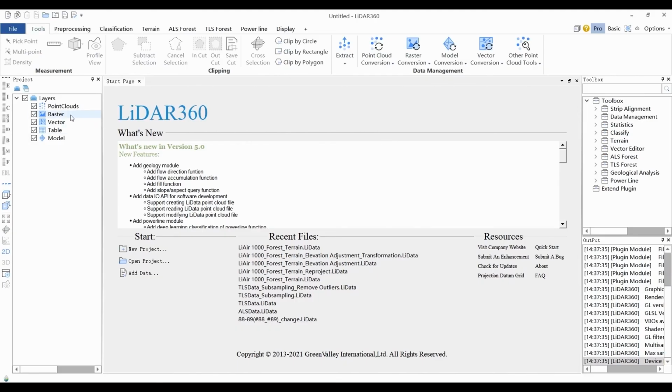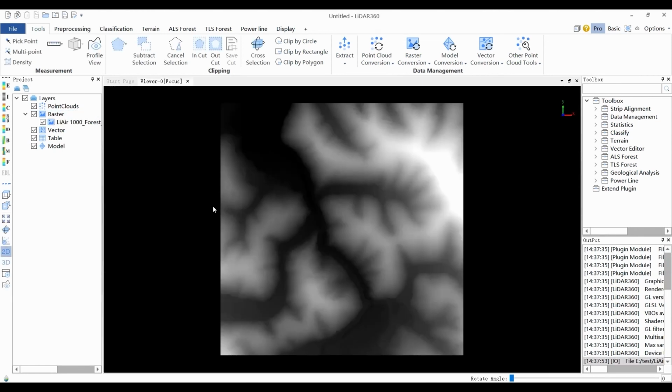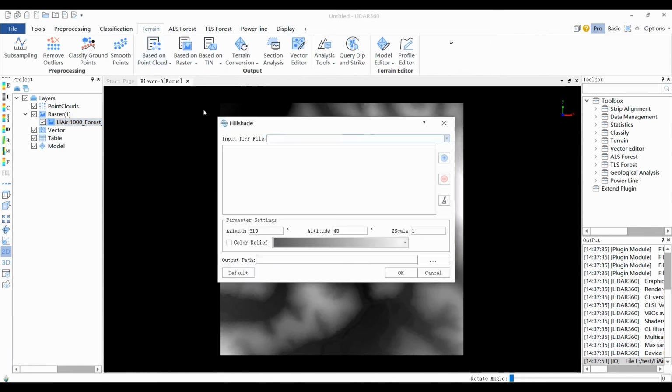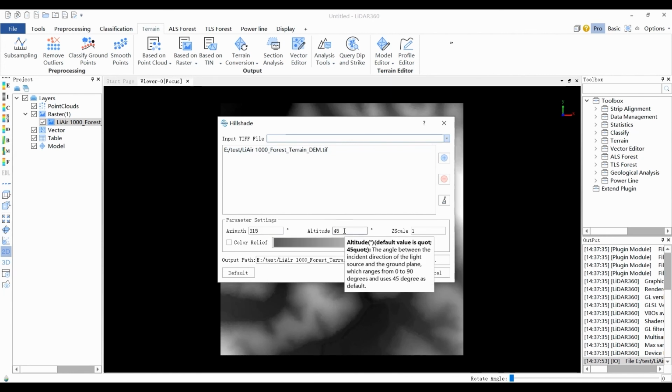The Hillshade tool obtains the assumed illumination of the surface by determining the illumination for each image element in the grid. The assumed illumination can be attained by setting the position of the light source and calculating the illumination value of each image element related to the adjacent pixels in the analysis or graphic display. The Hillshade tool can greatly enhance the surface visualization, especially when using transparency.